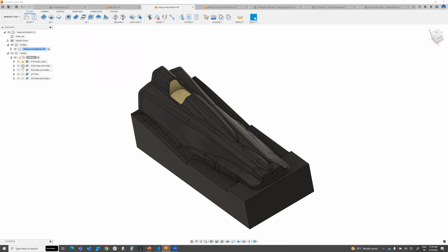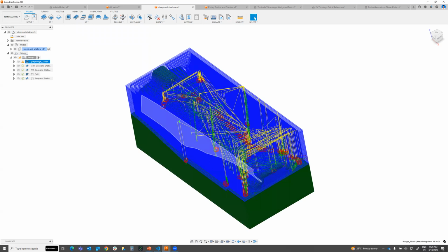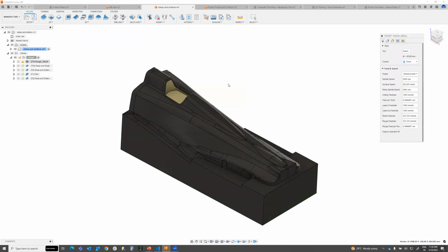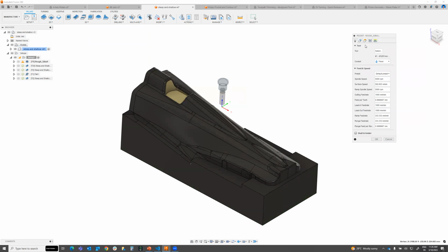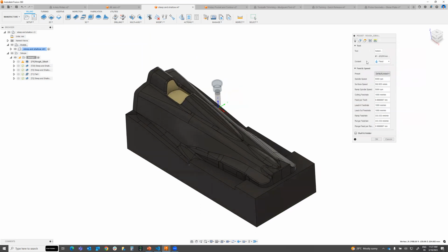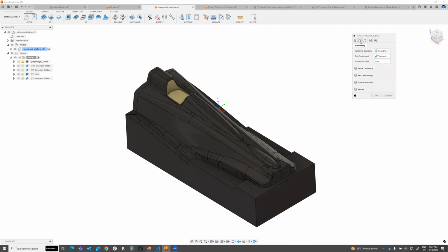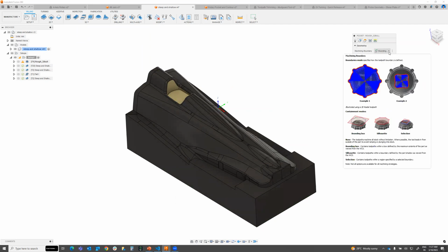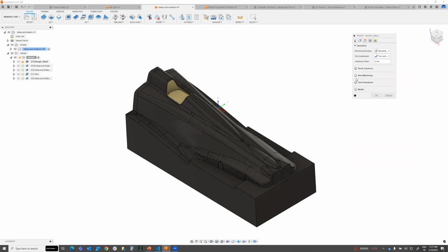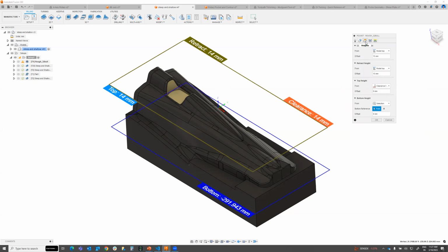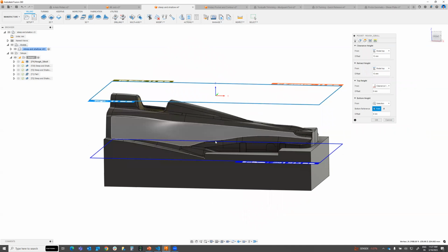As the first one, it is possible to generate your roughing toolpath, and in the roughing toolpath a lot of options are there to control your toolpaths. First is to define the boundary or the full model, depending upon the machining area. Then you can set your model top. I want to machine from here down to this level, so you can set your machining top and bottom height.